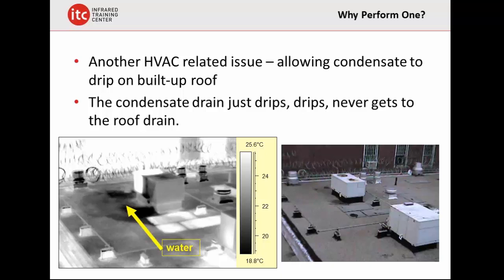Well, think about this. If you heated up several tons of rock, how long does it take for that amount of rock to give up its excess heat? It's going to take hours and hours and hours, isn't it? Well, the wet roof underneath is going to conduct its heat up through that rock. It's the normal process of conduction heat transfer. So it takes hours for that heat to come through while the rest of that roof is giving up its heat. Now, if you have a heavy overcast sky, you might not see it all night.